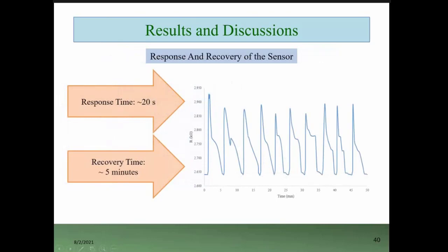And finally, with 10 cycles, the response and recovery time of the sensor was observed, and it was found that the response time of the sensor is 20 seconds. That means when we start flowing the fluid through the channel, the resistance was not changing immediately. It was taking some time, and the average response time is 20 seconds.